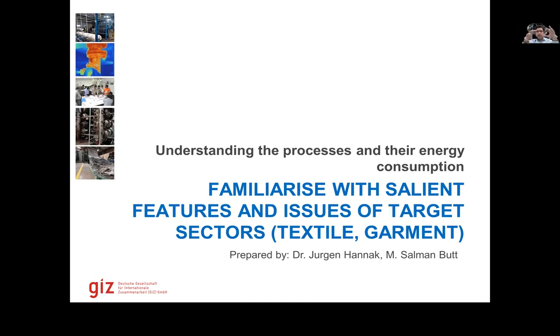So even if you are standing there in front of an alien machine, all you need to do as an energy auditor is to understand what different inputs are going in, especially the energy inputs, how this energy is being converted into useful work, how much of this energy is being carried forward by the product that we are producing, and how much energy is going out as waste.